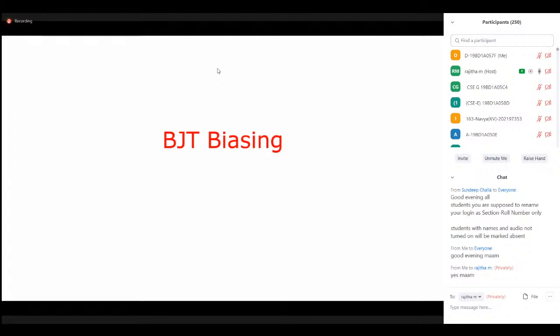The transistor is acting like an on switch, because the junction voltage drop is very small. The saturated voltages which you are applying at both junctions are constant, with a minimum amount of voltage from your output junction, collector to base. Then the collector current is your base current multiplied by beta, that is beta times IB. So it is acting like an on switch.